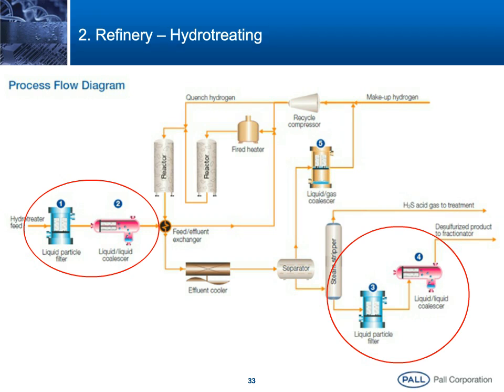We can see on the downstream side, the right-hand circle, on the steam-stripped diesel stream, the importance of effective liquid-liquid separation. This is a very challenging application because of the very, very fine water droplets that are formed due to the condensation happening downstream of the stripping operation. And the liquid-liquid coalescers in the Aquacep family have been proven very, very effective here.